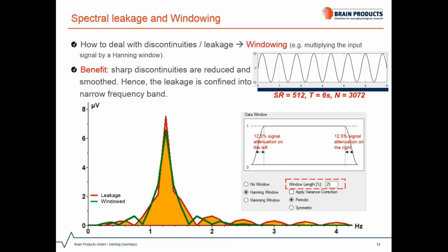Good that we have resolved the leakage issue. However, we are still left with one final issue, and that is not only the energy of the signal is reduced, but also the amplitude has been even more reduced due to windowing. Generally, correction factors can be used to compensate the variation caused by windowing. So the important message here is that while thinking about frequency domain representation, it is necessary to be aware of spectral leakage. And to overcome spectral leakage, it is recommended to apply windowing.